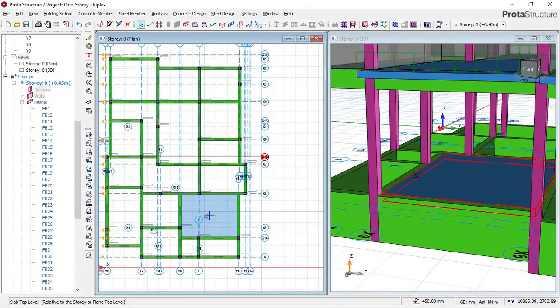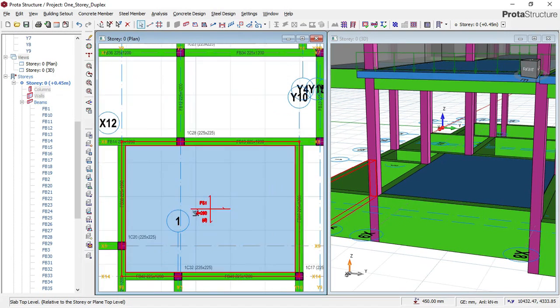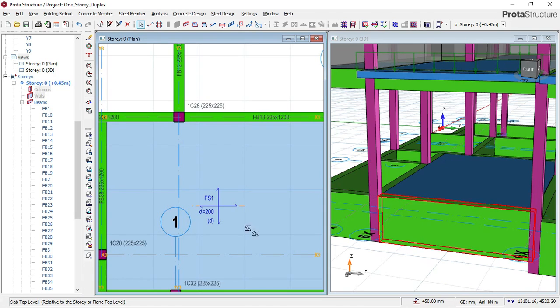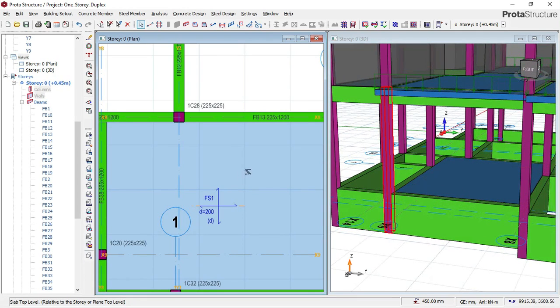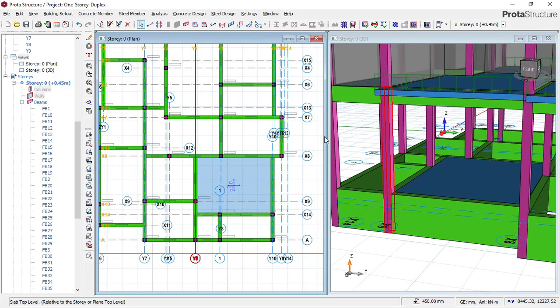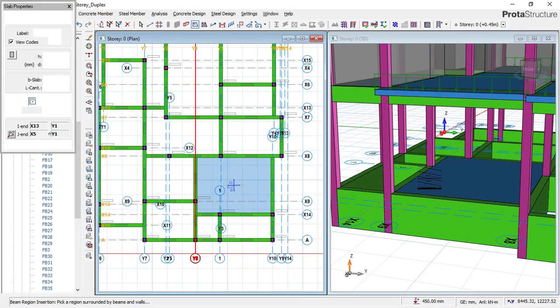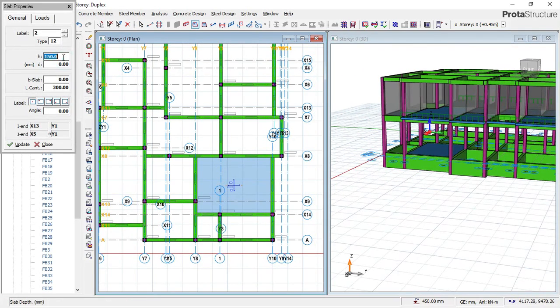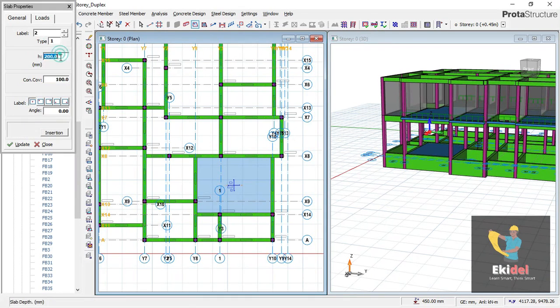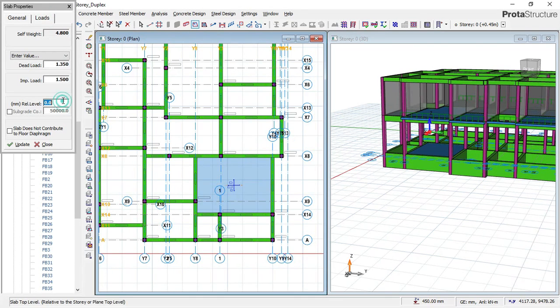So you get this level by simply doing the depth of your beam minus your assumed depth of slab, which is 200 in this case. So 1.2, which is the depth of the beam, minus 200, gives me 1000 millimeter as my relative level. With this, I'll click back to slab and begin to insert slab in every area of these panels. I'll put the properties which I want, 200 of my depth and my relative level to be 1000 millimeter.